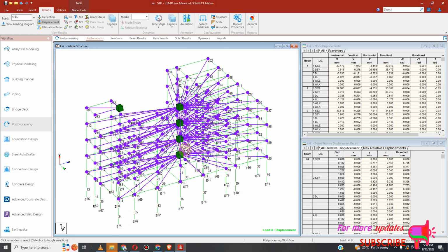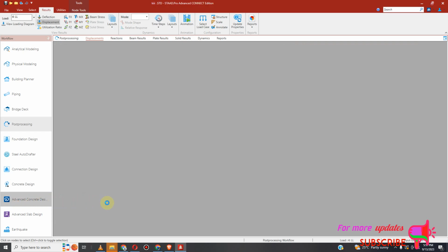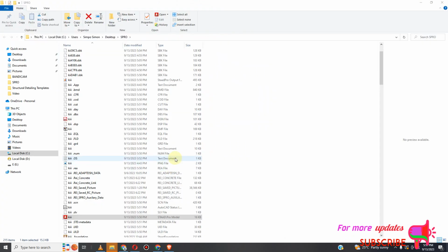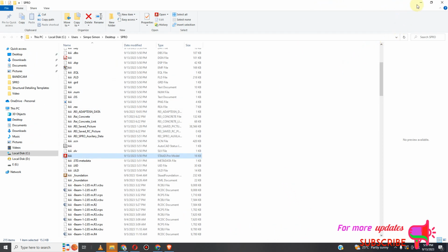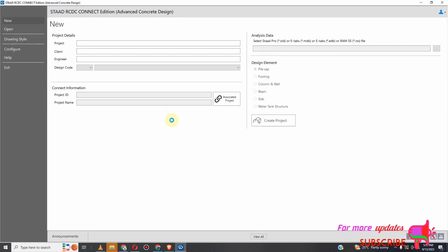So after that, now you can go even to RCDC. I uploaded a video where RCDC was taking a lot of time to load. But I'm sure now it will not be hanging, because the model is now okay. So for the purpose of those who viewed that video, I'm going now to demonstrate how we solve that problem, which was that my RCDC was taking too much time, because my model had an issue. So you see that master slave node is very crucial in STAAD.Pro.